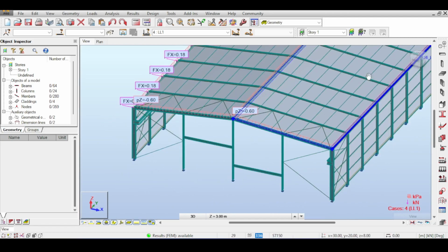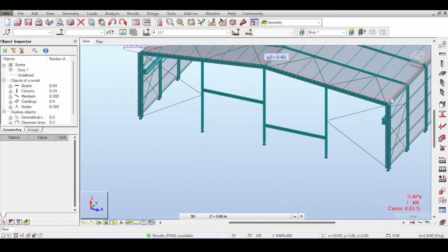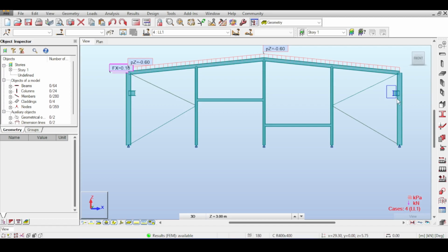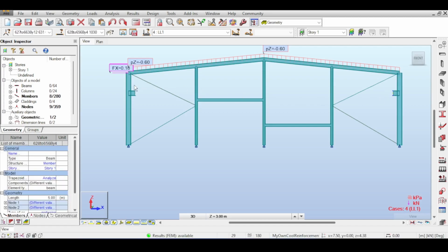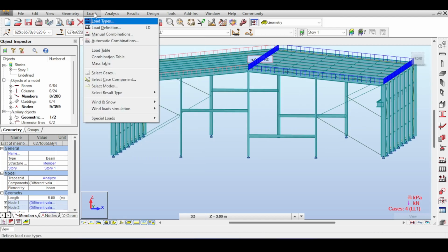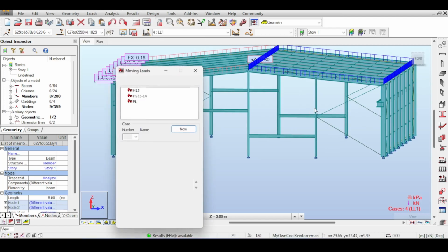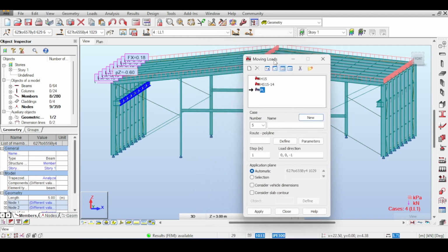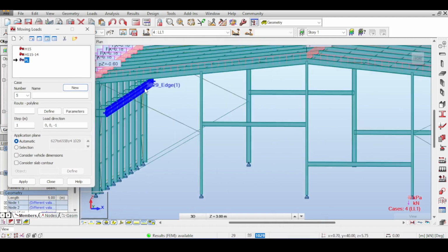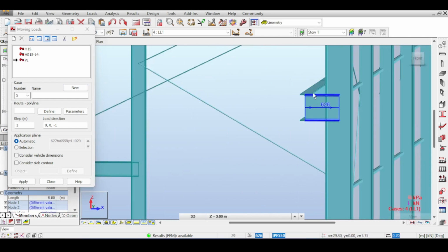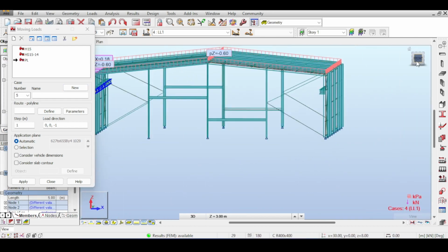The first discussion point was about our dear subscriber Donald Khanye and member, who correctly said that, wait a minute, you have a moving load here, which is the crane, and a moving load here, which is the crane. And the problem with the moving load definition in the loads, special loads, is that those two moving loads are disconnected, like they don't move in unison, meaning that one of the cases that will get analyzed might have a point load at the very far end on this side and the near end here on this side, which is impossible because the crane moves in parallel.